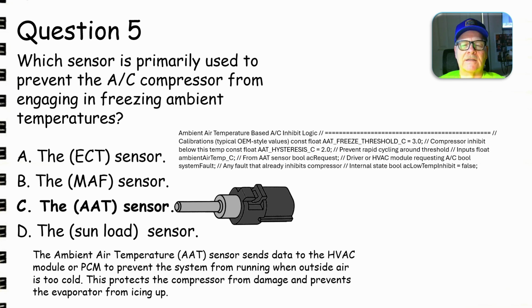Something else I always liked to do was take either the scan tool, or on the older ones that didn't have data stream, on a front wheel drive car, like a Taurus or something, I would back probe the engine coolant temperature sensor and watch the ECT voltage. When it dropped below 450 millivolts the fan would kick on, and when it warmed back up to like 480 millivolts the fan would kick off.